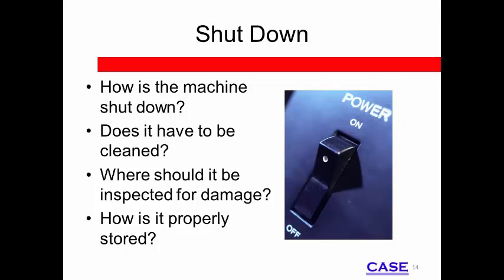Once the job is complete, the proper shutdown procedure should be completed. This includes disconnection from power, cleaning the tool, inspection for wear, and proper storage.